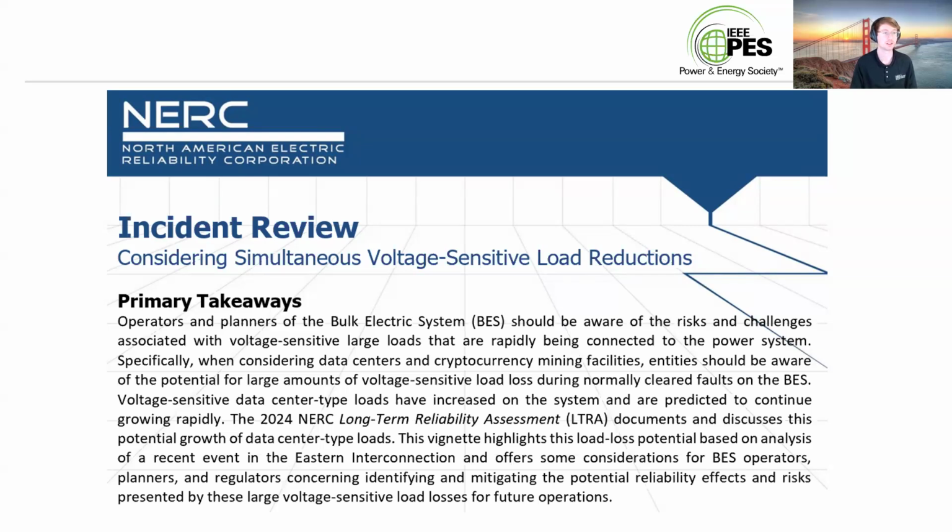I would encourage you to go to the ERCOT LLWG and find the presentation. They found a specific number. I think it was 2,000 megawatts for voltage stability in a specific area of their system, which is highly local. And then they found 2,600 megawatts as a frequency stability limit. There are a lot of different ways to look at it, and those are just two specific ways to look at limits. Then they need to know who's going to trip, and whether we're going to hit that 2,000 megawatt trip due to the most severe fault.